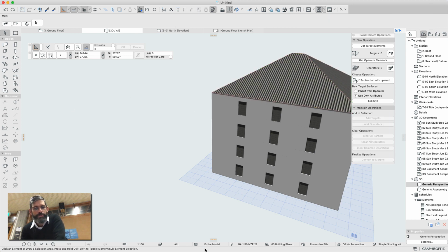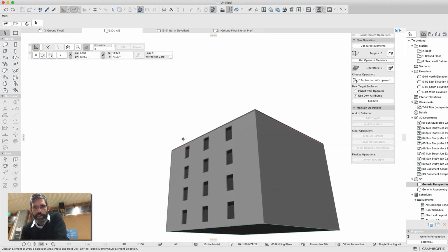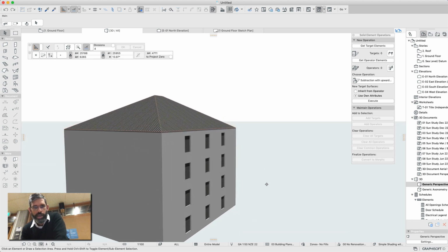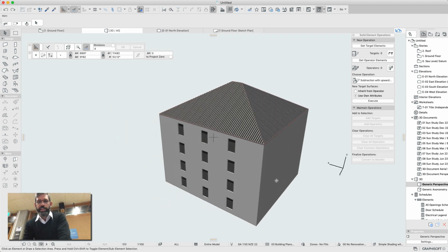Okay, so we've effectively now made our model, and she's all ready to go. So if we're going to 3D print this, we can go straight out to STL. We can actually scale it when we go to STL. And you can go down to level 4 and the DARH and go, here's my STL, it's at 1 to 100. They go and open up, and hey, cool, look at that. And they can go and print it. And it'll all just be one nice little solid block with the windows. Phew!